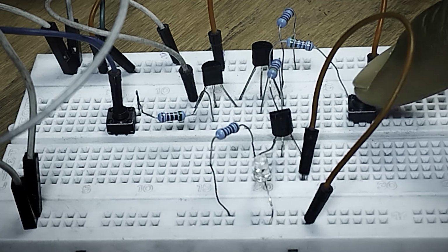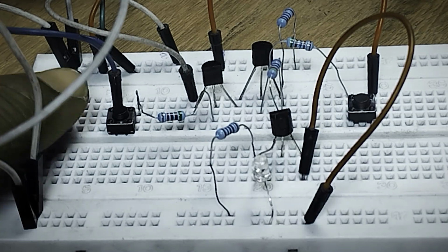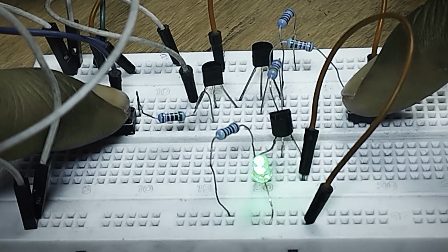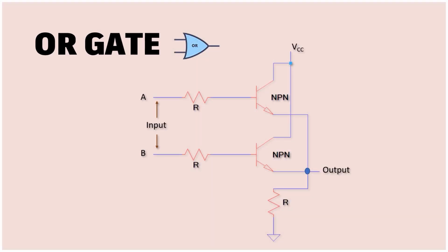Alright, so you can see I press the first button, no response. Second button, no response. But pressing them together, we have our LED turned on. Okay. Next, the OR gate.